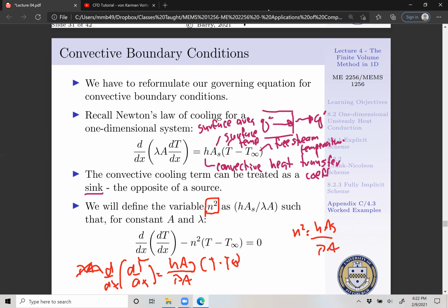Imagine we have this rod and we have cooling going down the entire length of it. In this situation, as opposed to modeling just a Neumann boundary condition on the end, we can model a Neumann boundary condition over the length of our domain. And what's incredibly amazing about this is our sink can be dependent upon the temperature of our cells.